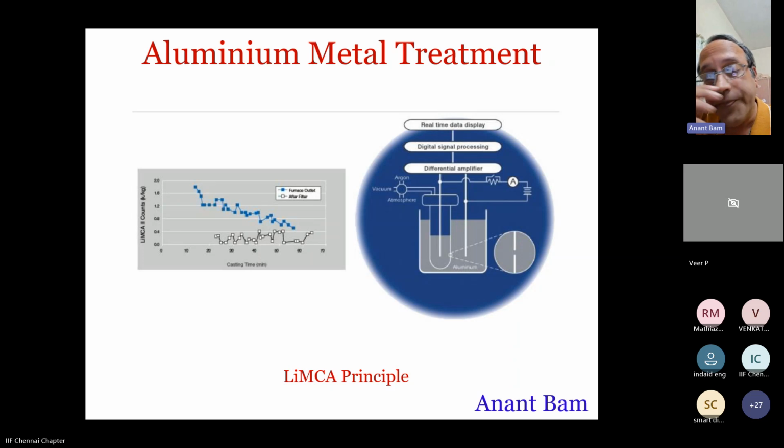As we all know, aluminum in any condition, in any state, is a good conductor of electricity. So this liquid aluminum itself becomes a conductor. And the cross-sectional area of that orifice, that small hole at the bottom of the tube, becomes the area of the conductor.